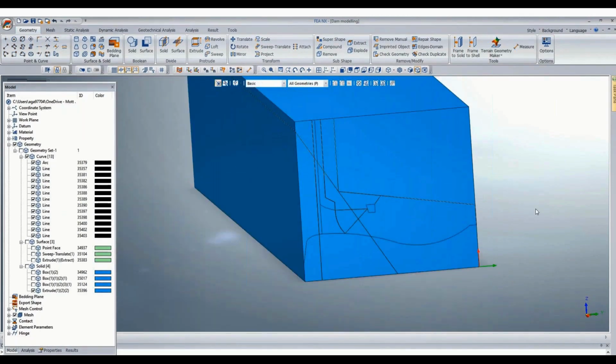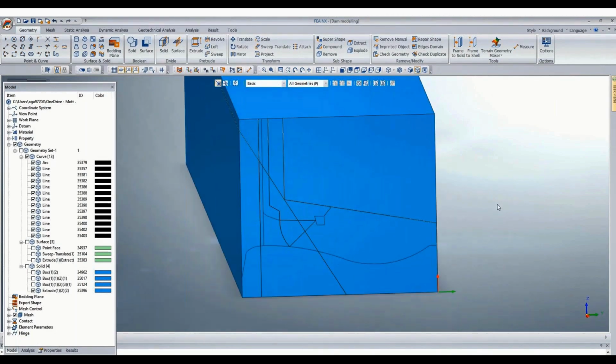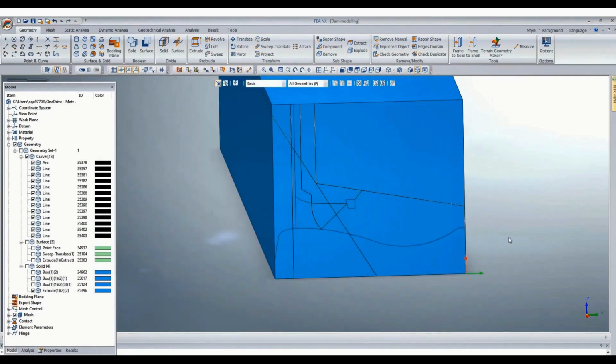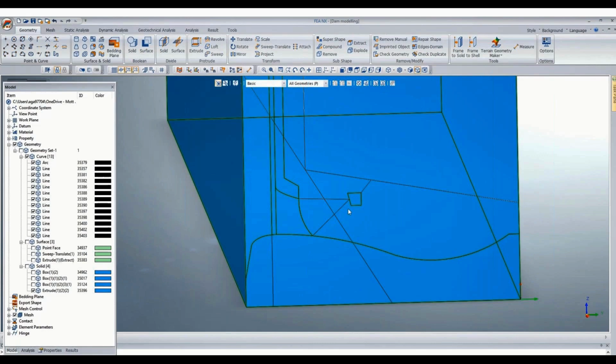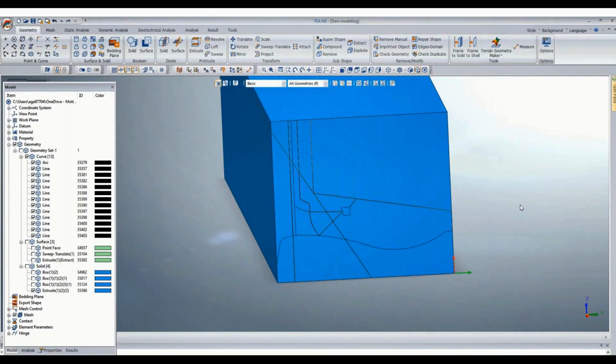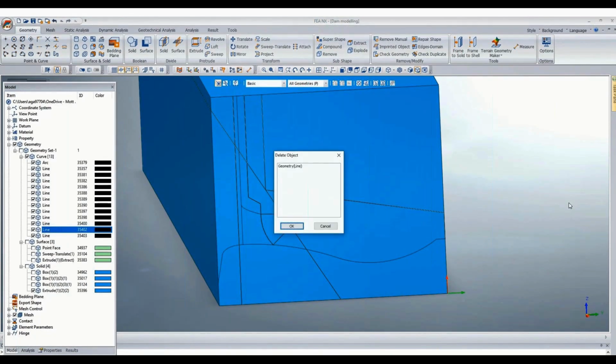See, this profile, this pier profile, it is dependent on the nappe profile. So I'm presuming that this nappe would be lower than this, and MWL I have considered at higher elevation at the downstream end, higher than the maximum tailwater level. Anyways, I'll keep this profile for the pier.